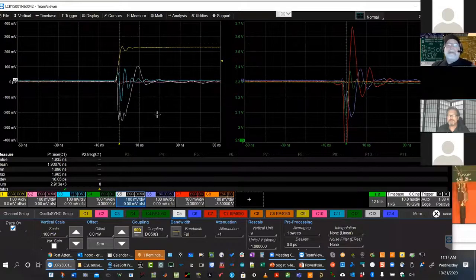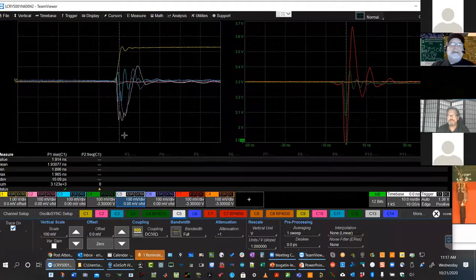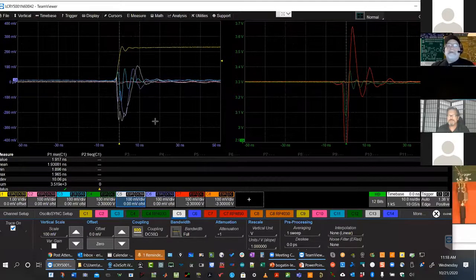We look on the package, and here we are in 6. We'll look at the package noise, and you can see the package noise just about the same as the board noise. Yeah, we have this same amount of package noise, but it's hidden inside the board noise. A lot of ground bounce noise because of poor layout. Well, this is looking at ground bounce. Now we're going to look at the power rail noise.